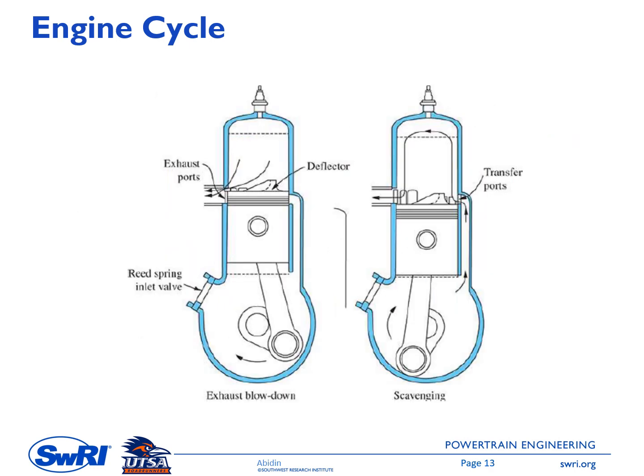In a four-stroke engine, to have one complete cycle, the piston needs to move down to BDC doing the intake stroke, then move up doing the compression stroke, then move down again doing the power stroke, and then move up again doing the exhaust stroke. So this means that for one complete cycle, the engine needs 2 crank rotations, which is 2 times 360 degrees. So for a four-stroke engine, one complete cycle is done by 2 crank rotations.